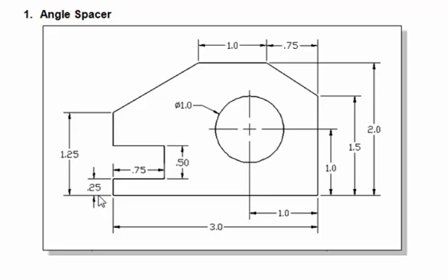Although it is possible to set up the snap and grid display increments to smaller increments, such as 0.1, the problem is, if you make the increments too small, it's actually more difficult to get the distance that we want. In this case, using the 0.25 increment is a good choice. My plan is to start from this upper left-hand corner of the design and will simply draw line segments by going all the way around to create this design.